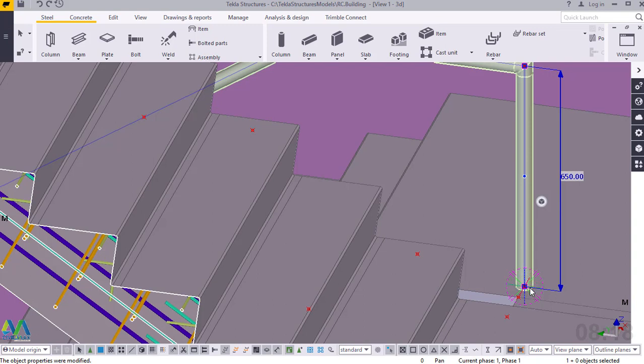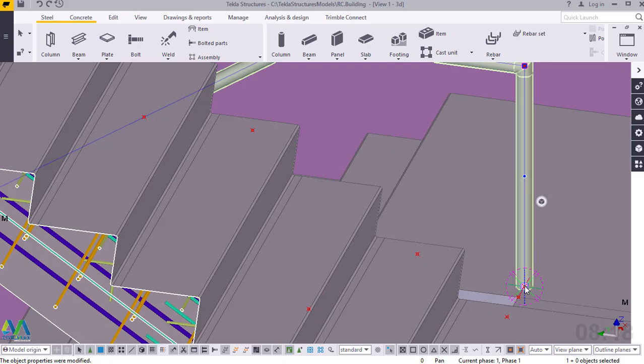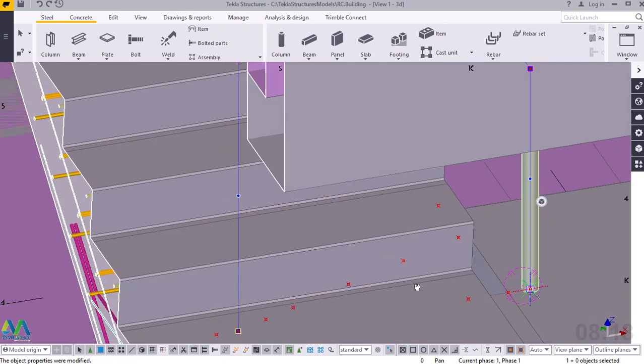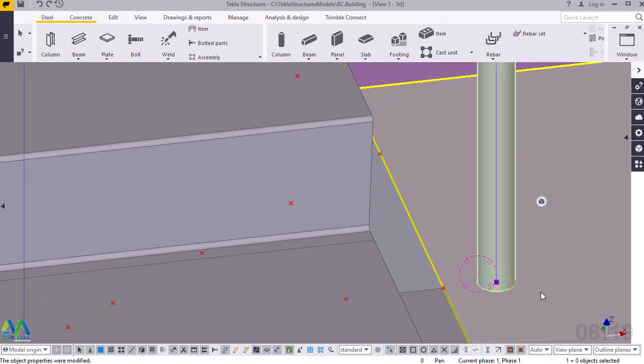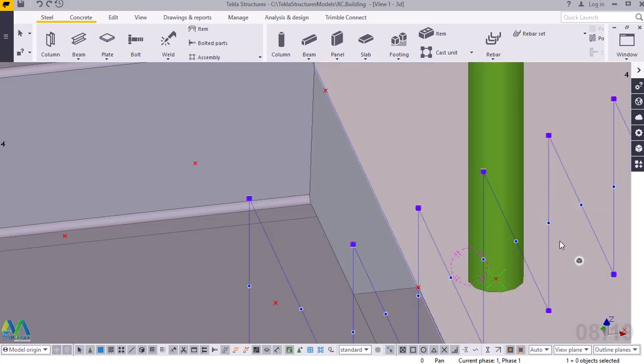Now we want to make sure that the pipe is sitting right at the center of the points that we placed on the staircase. Now I'll press Control and the middle button on my mouse so that I can turn this and take a look at how it has positioned itself with our points. Now it's sitting right on the points we placed as a guide.